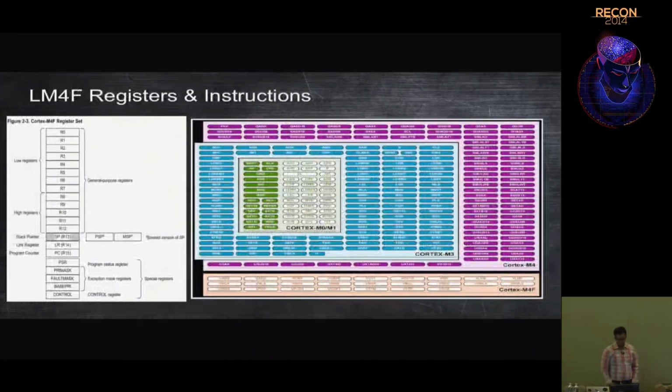So I won't bore you with the details, but basically a Cortex M4 is kind of like a standard ARM processor, except it's less complicated. It's got less execution modes, it's got less instructions, and it's a lot simpler than a full-blown ARM processor. So these are meant as microcontrollers for things like embedded robots and things like that. They're not meant as fully blown application processors because that would be overkill. But you still have access to an FPU. You have access to over 200 instructions. You have your 16 registers. So it's a very powerful platform for actually writing code on it.